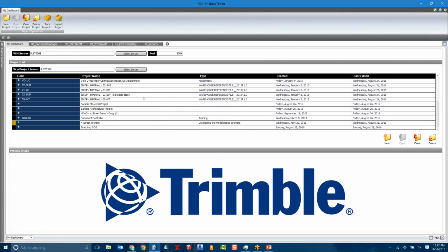One important thing to note here on this screen is that every view that you have in Vico has a ribbon. And in particular, on this ribbon, one thing I want to point out is our packing and unpacking. BIM models can be big. So within Vico, we're able to pack those projects. You can archive them, save them for later. You can also collaborate with teammates and send them out in this way. So it's almost like a zip for models, if you will.